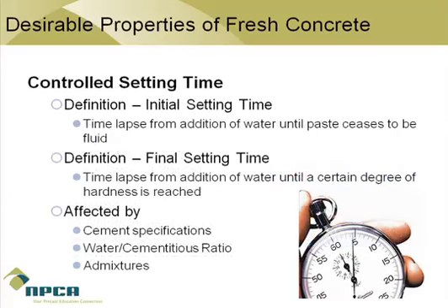Concrete setting time is important to precasters. The faster concrete sets up in the form and reaches the specified stripping strength, the faster the form can be stripped, cleaned, and set up for the next pour. What do we mean by setting time? Well, there's a difference between setting and hardening.